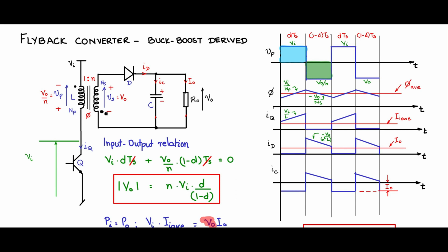When the diode is on, there is V naught across it, and on the primary side it is V naught by N with plus minus in this fashion, plus this Vi. So you have Vi plus V naught by N together coming across the collector emitter of Q. You will have to rate the VCEO rating of Q to be greater than Vi plus V naught by N.